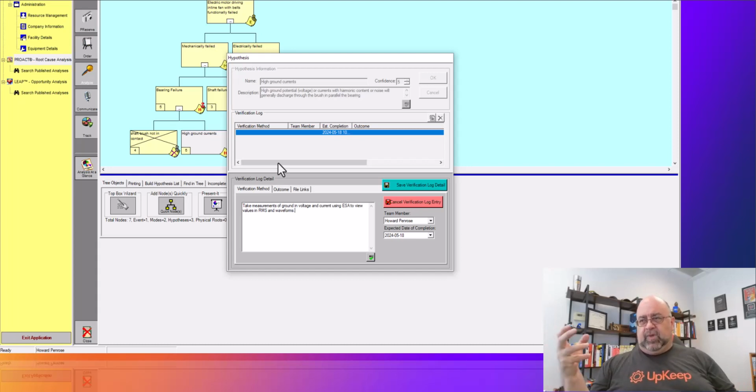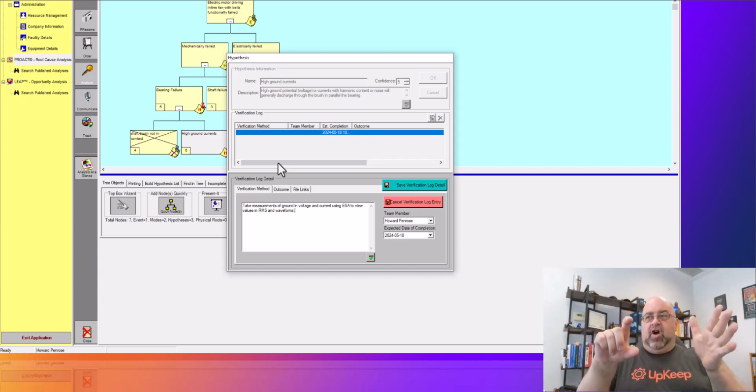the bearing. But also what happens, and most people don't realize this, is that just because I put a shaft brush there, if I don't insulate the bearing, I have a capacitance and resistive circuit on that side, and I have a resistor, because I'm not 0 ohms, in parallel with it. All I've changed is the RCL circuit, meaning that I still have discharge happening in the bearing, but at a much lower value. Now, if I put a dielectric material on there, I'll adjust it even further and reduce it,